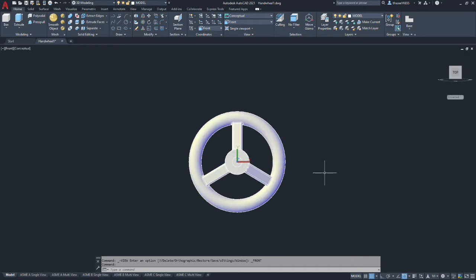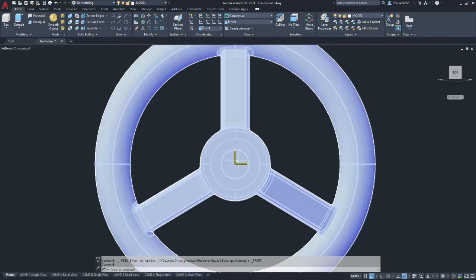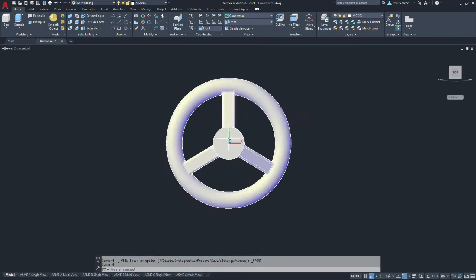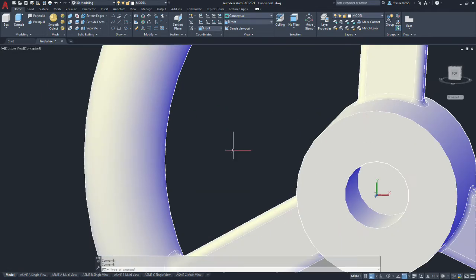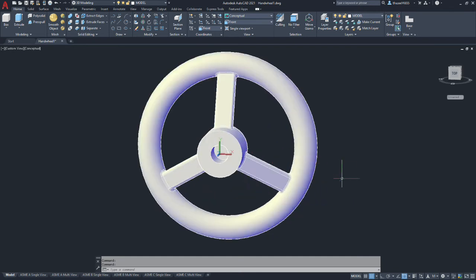Now, if you drew it the same orientation I did, you should be looking at the back of the part and straight in on the hole that's in the back. If you didn't, that's fine. You would do your shot from the opposite angle. But the goal is to try to have a limited number of hidden lines, and in the example, that feature is a hidden line. We want to do a better job.